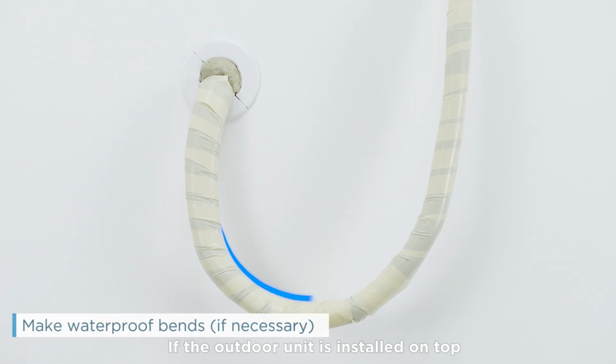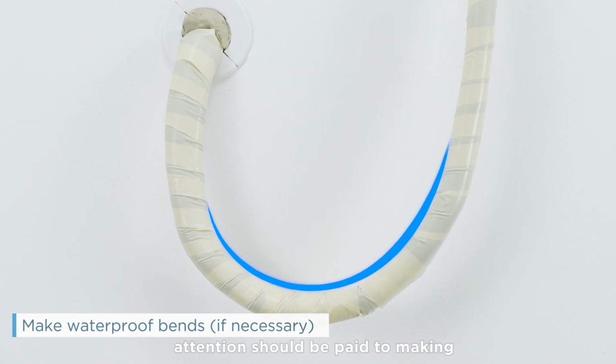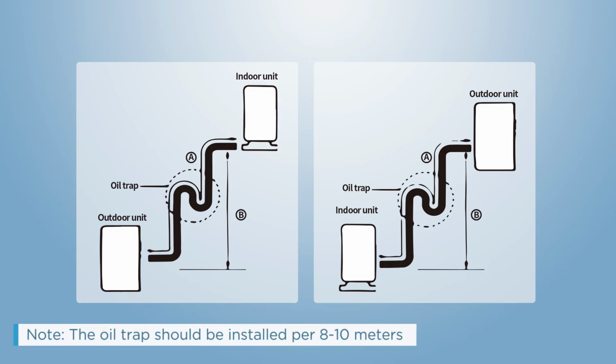If the outdoor unit is installed on top and the connecting pipe enters the room through the wall hole from above, attention should be paid to making a waterproof bend to prevent water from entering the room. Make an oil trap if necessary. Note, the oil trap should be installed every 8 to 10 meters.